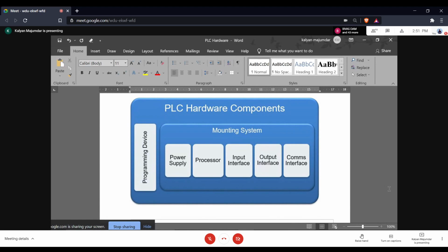Indicators could either be on, it could be off. A solenoid valve can be on, it could be off. A relay or a contactor could be on, could be off. So again, you have hardware that converts the output of the processor into a signal that can drive any output device, lamp, relay, solenoid valve, contactor, and so on. So such outputs are referred to as discrete outputs because such outputs can only take on two states. One is logic state 0, the other one is logic state 1. A second category of inputs and outputs are referred to as analog inputs and analog outputs.